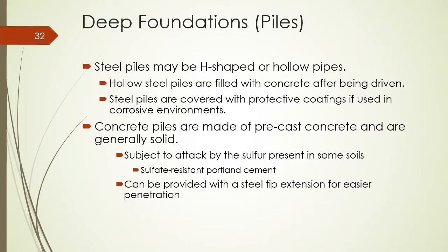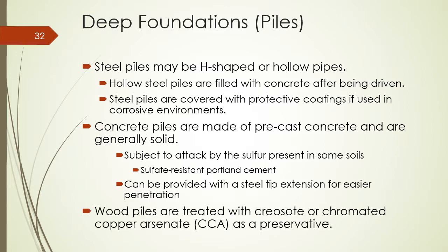They may have a steel tip to prevent the concrete from being damaged as the concrete piles are driven into the ground. If wood piles are used, they are usually treated with creosote or chromated copper arsenate, CCA, as a preservative.